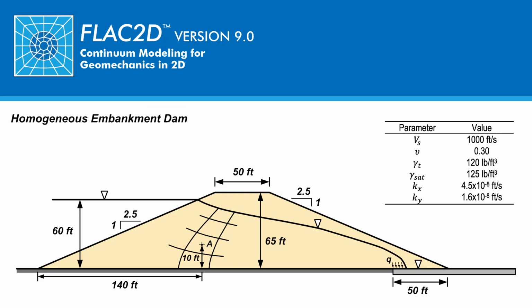This completes the first step of our analysis, establishing the stresses in the dry embankment. In the second step, completed in the next tutorial, a steady-state seepage analysis will be conducted to calculate the pore water pressures in the embankment due to the reservoir. In the third step, completed in the last tutorial, soil densities will be updated and the effective stresses in our model recalculated.